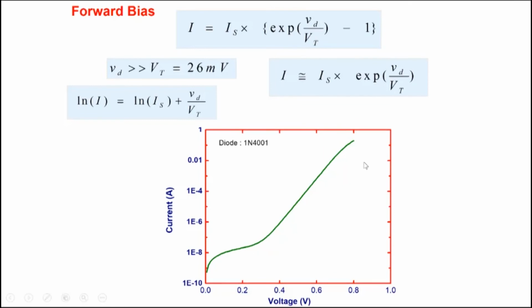When we are using a diode, if we are in this particular region or this particular region, it may not obey this simple exponential characteristic. But if we are in this particular region, then it obeys the exponential relationship we are talking about. Now, it may have n equal to 1 or some other value, but it's an exponential characteristic. So there's a range of voltage and current over which a practical diode has exponential characteristics. Go to very low or higher voltages, and it's no longer this simple.